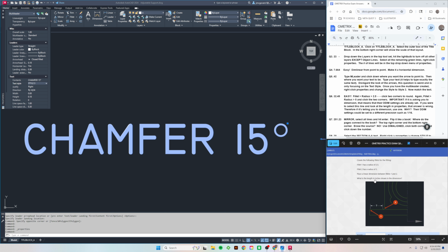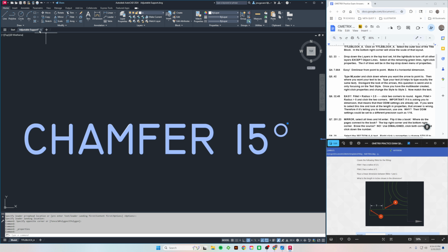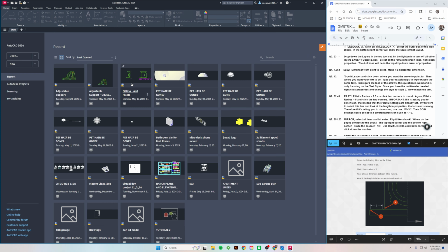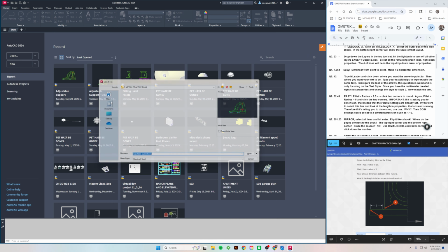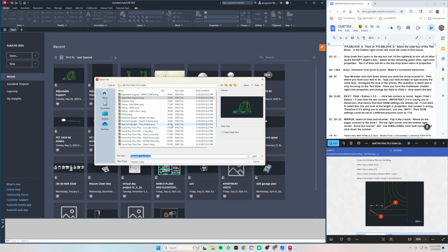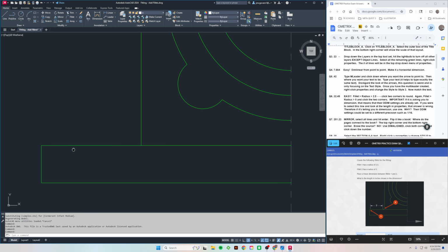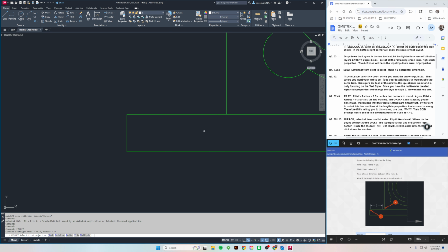Number 6 wants the fitting add fillets file. You guys should know fillets. Super easy to do, but sometimes I still have to tell you guys, don't forget to hit radius, right? So going into open, again, that was the fitting add fillets, okay? And it wants you to add fillets, I believe, on this area over here. Fillet, okay? Don't do fillet edge, that's for 3D modeling. This exam has nothing to do with 3D modeling.